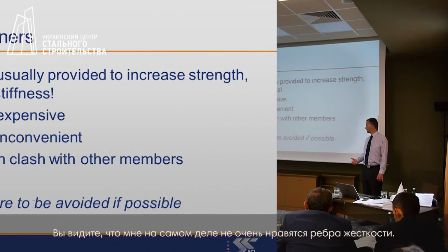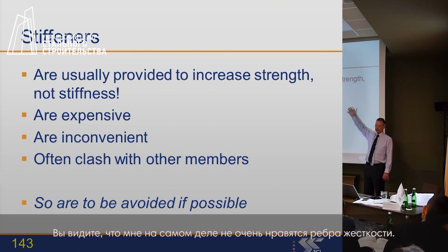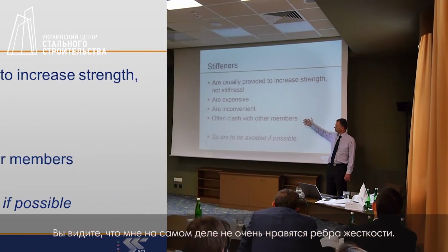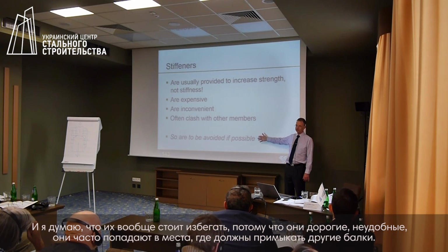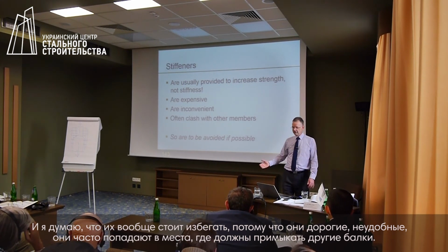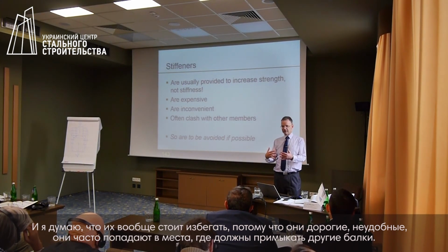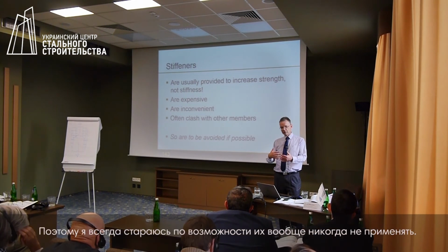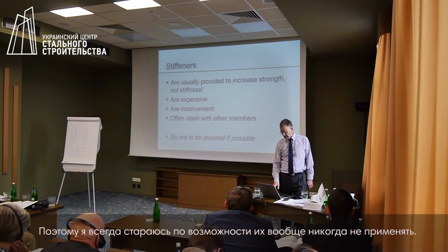So you can see, ladies and gentlemen, that I get rather excited about stiffeners. My view is that they should be avoided because they are expensive, they are disruptive, they clash with beams coming in the other direction, and I would try very hard to avoid them if I could.